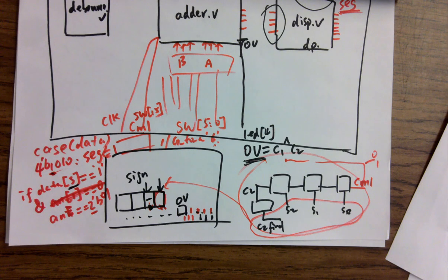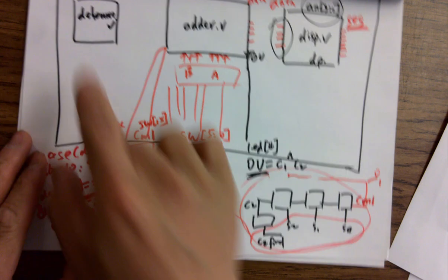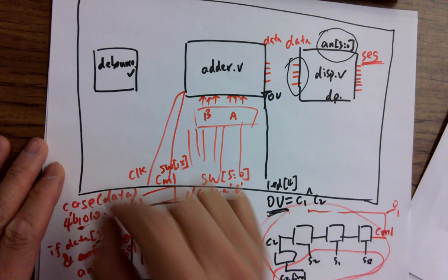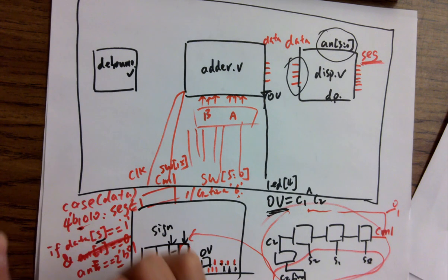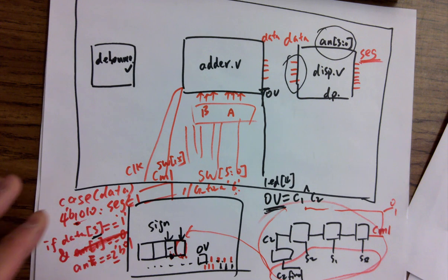It's going to take a lot of time to put the numbers in. So it has to be serial input, right? That's why we do a serial in, parallel out. So you just need one switch as a clock and another switch as an input. Just one pin input, serial input. So that's task 2 and 3.